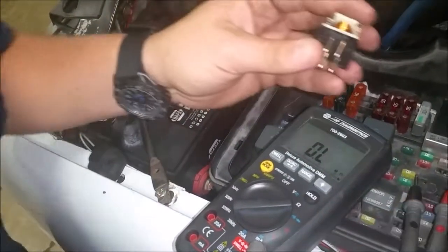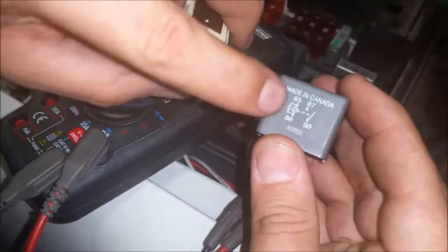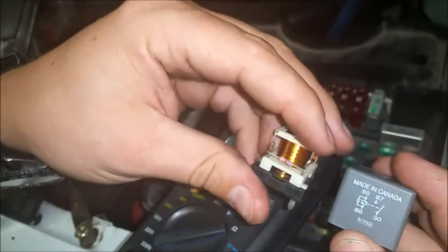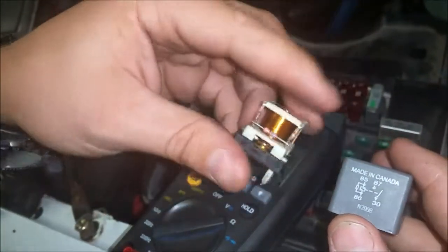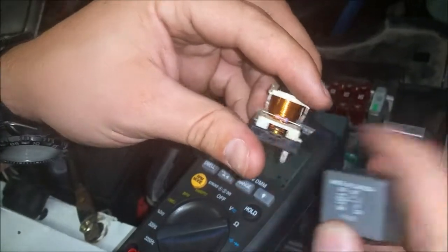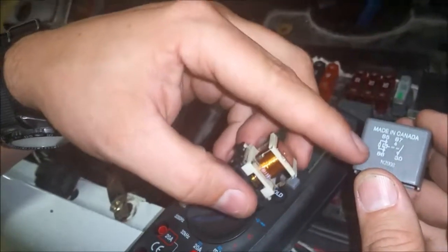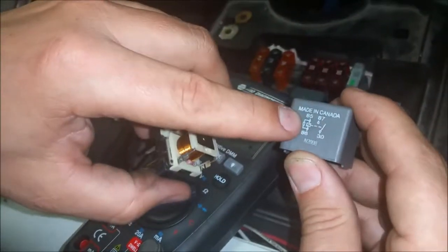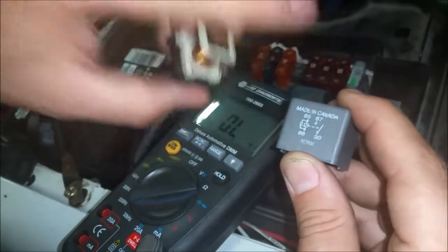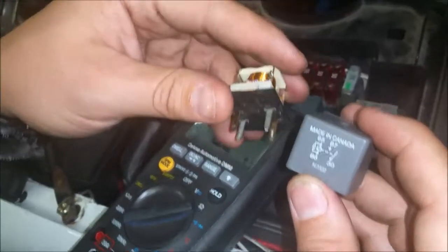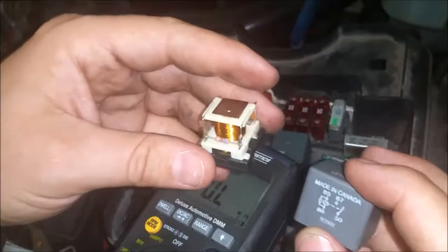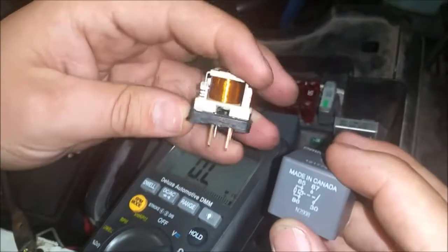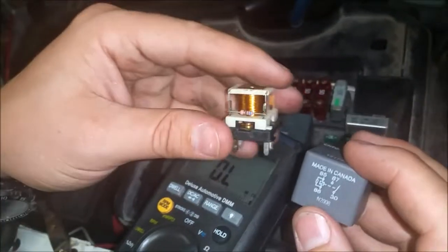And if you look on the casing that comes with this relay, it's got the coil, but it also shows a resistor on the outside of that coil. Here we go, there's the resistor. So there's our coil with the resistor, and here's our switch. So the low power side, 85 to 86, which is our controller, creates electromagnetism, which pulls over our switch on 30 to allow high voltage to go through the relay. So it's a simple makeup of it.